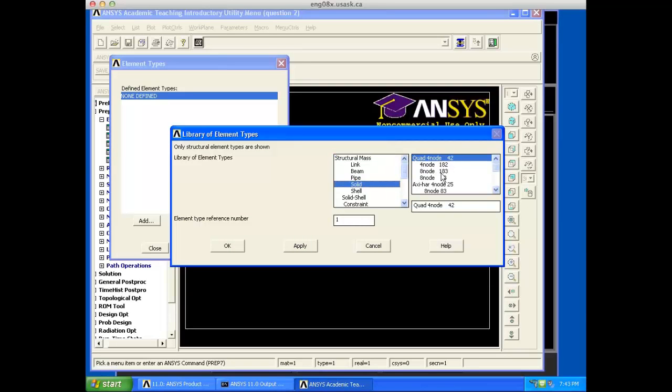Here we have different solid models. We have like 2-node and 8-node. Well, here we just select 4-node. It's good enough, and the 8-node maybe is more accurate, because the 8-node will give you the edge, which can deform quadratically, not only linearly. But here we just use 4-node. Let's click OK.